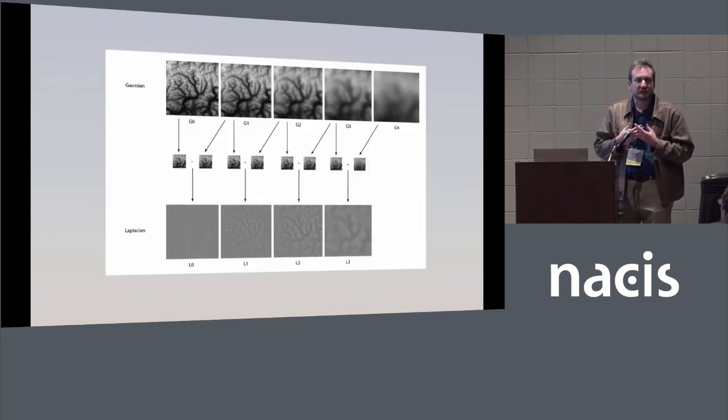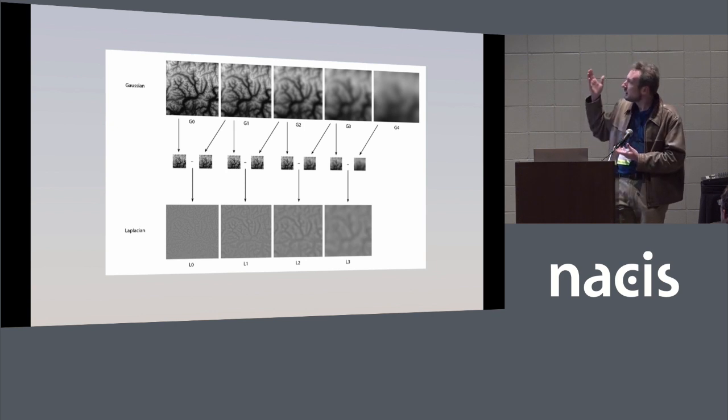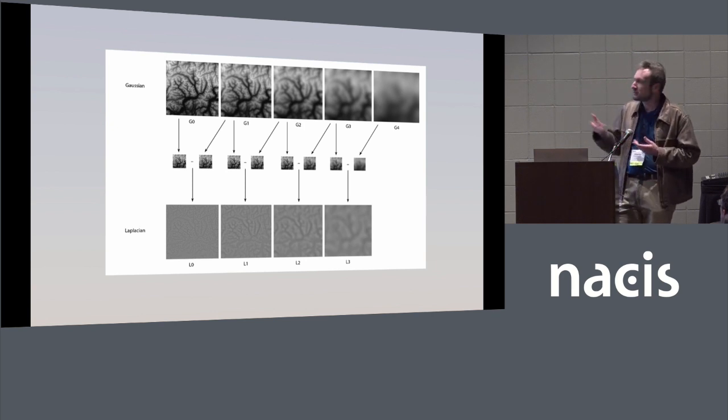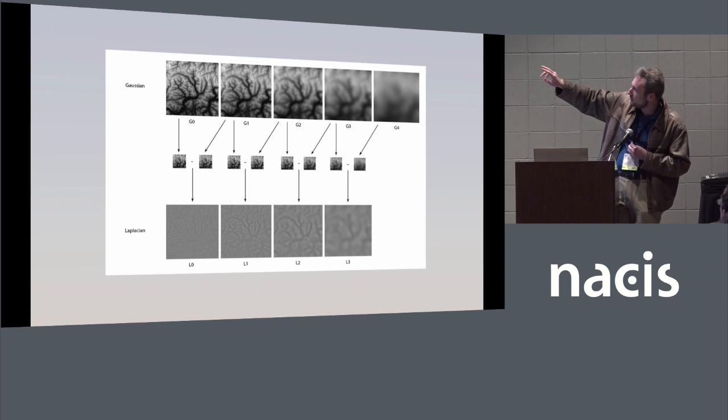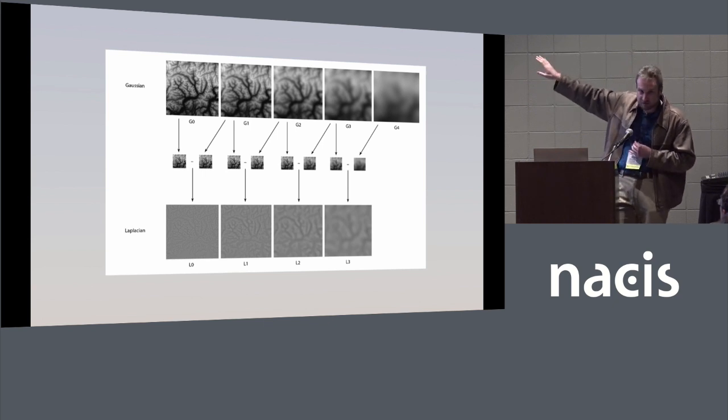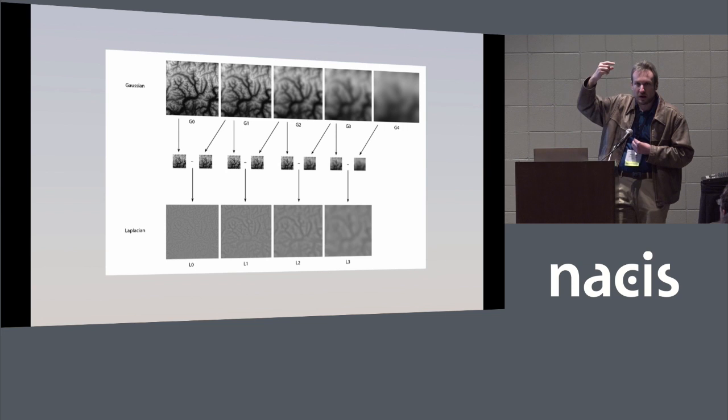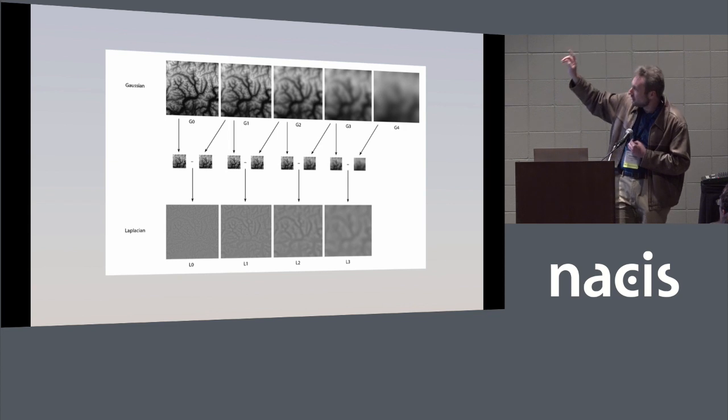Pyramid Shader is a utility that Bernie Jenny, myself, and Jim Maynard, and a bunch of others at our cartography and geovisualization group have created. It's been talked about a lot so far in this conference. The way that works is you take a DEM and you run a set of Gaussian filters on it. They're different sizes. The first one is a radius of 1 pixel, then 2, 4, 8, 16, doubles every time.